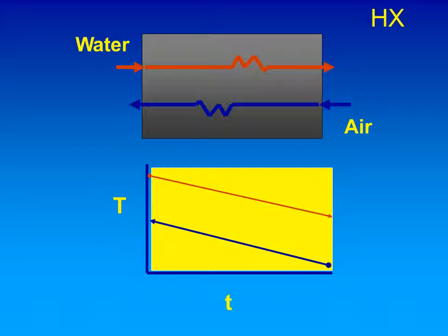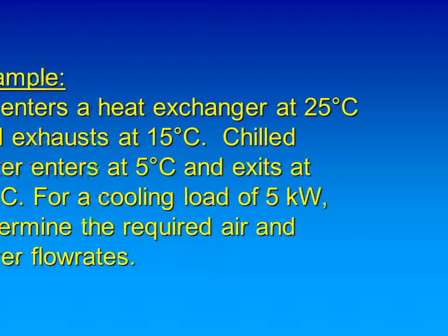Now, all along this heat exchanger, physically, at any point in this heat exchanger, the hot has to be hotter than the cold, and this temperature difference we call the driving force for heat transfer. The greater the temperature difference between the air and the water, or the water and the air, the faster the heat will transfer, and the smaller your heat exchanger will need to be. And that's important in design for later on.